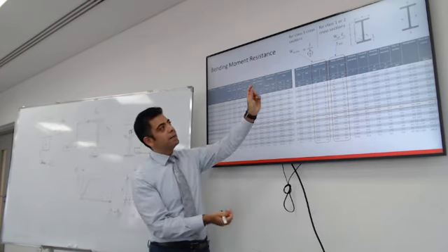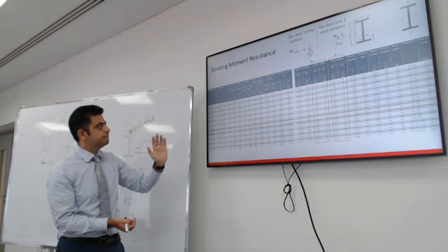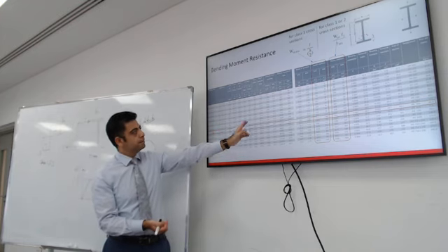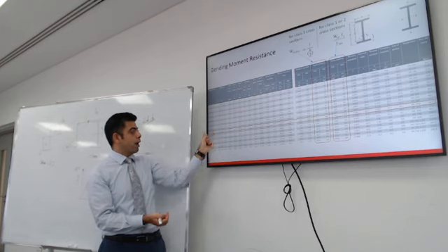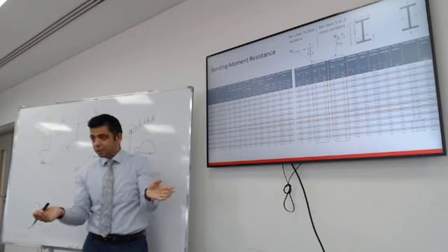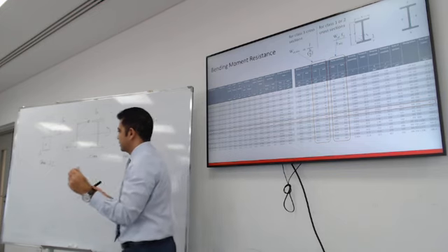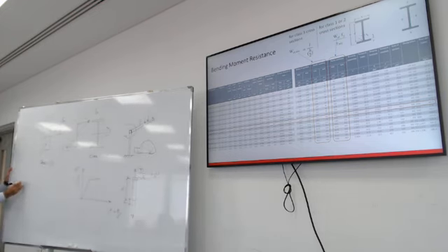Do we know the thickness of the flange, TF, for IPE 400? Yes, it's given. TF for IPE 400 is 13.5 millimeters. So the manufacturer will build them with this dimension. All right, so how do we get the section modulus? The elastic section modulus is the moment of inertia divided by h divided by 2, half h. This is W elastic.